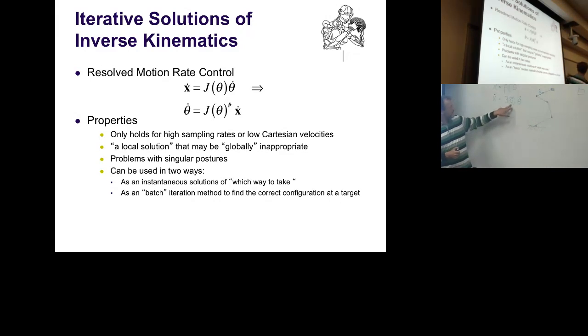The Jacobian depends on theta and changes all the time. So it's a matrix which non-linearly depends on theta. I don't want to call it a non-linear matrix. That makes no sense. Okay? That means you cannot just say, I'm here, and I take one Jacobian and keep on moving in this direction, hoping to get there. That's not going to happen, since after just doing a small little step, this Jacobian is not valid anymore. So you have to recompute it all the time.